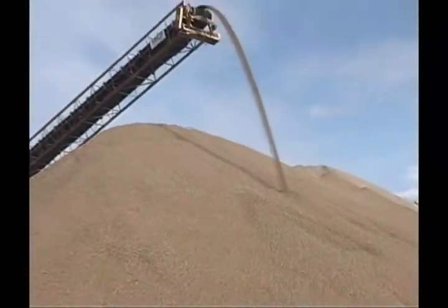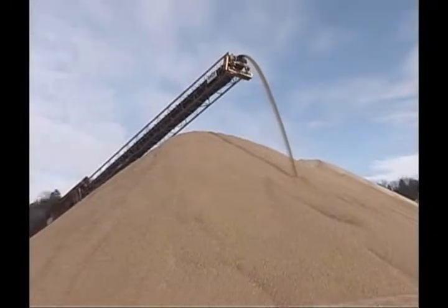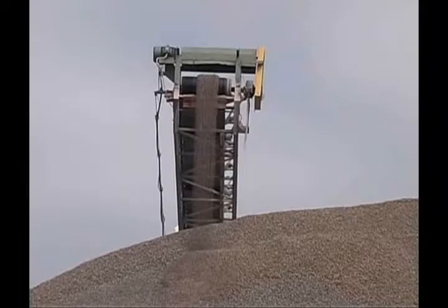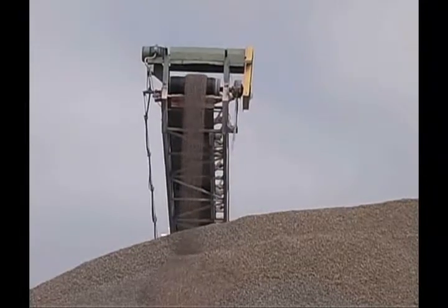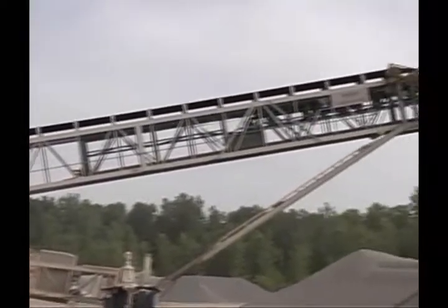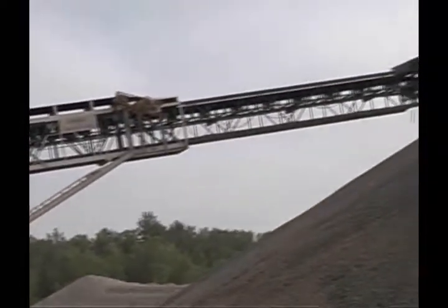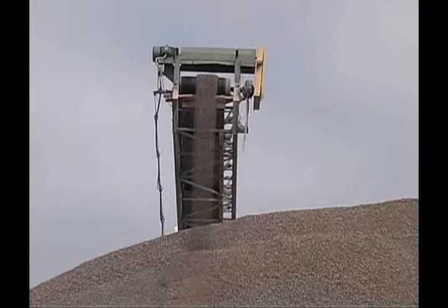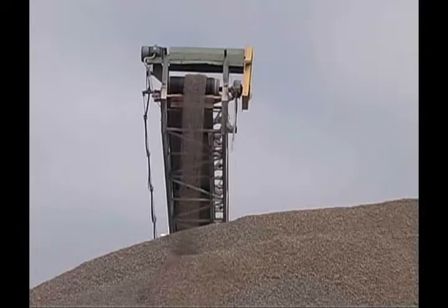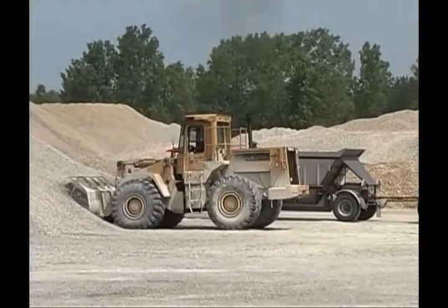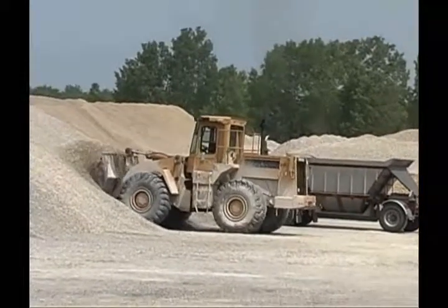Coarse material tends to roll to the outside of the stockpile, while finer material is retained in the center of the stockpile. Segregation can be reduced with proper conveyor operation. Starting the pile in lower lifts and gradually raising the conveyor while moving it horizontally can minimize segregation. Radial stackers have proven to produce uniform stockpiles and to reduce segregation. Segregation can be corrected by proper loading practices when removing material from the stockpile.